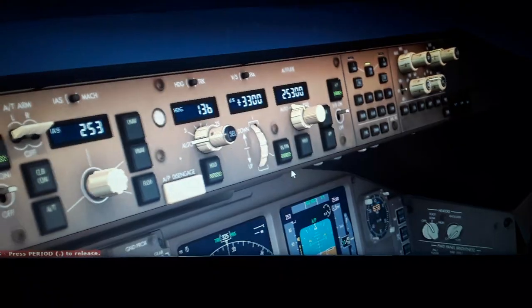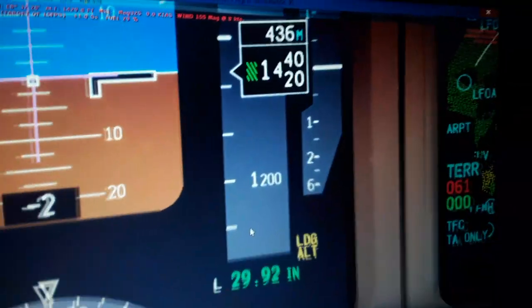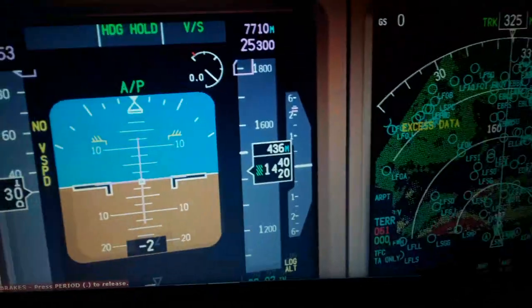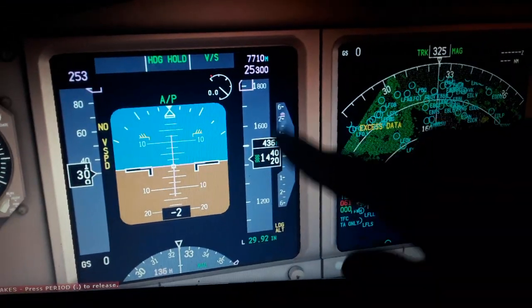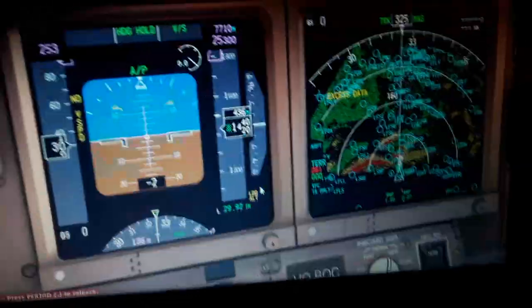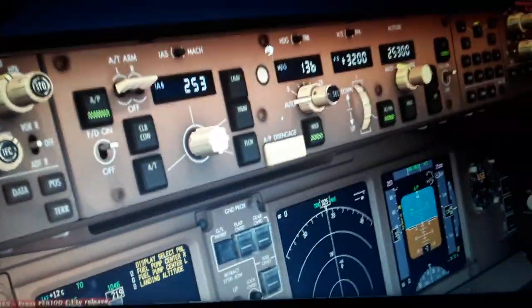you will see like 2,200 over here, the tick mark for the positive climb in tens, hundreds and thousands of feet per minute. So the needle will move all the way up here after the takeoff in the VS, the vertical speed mode, with the heading hold. We can also set the autopilot disengage now.